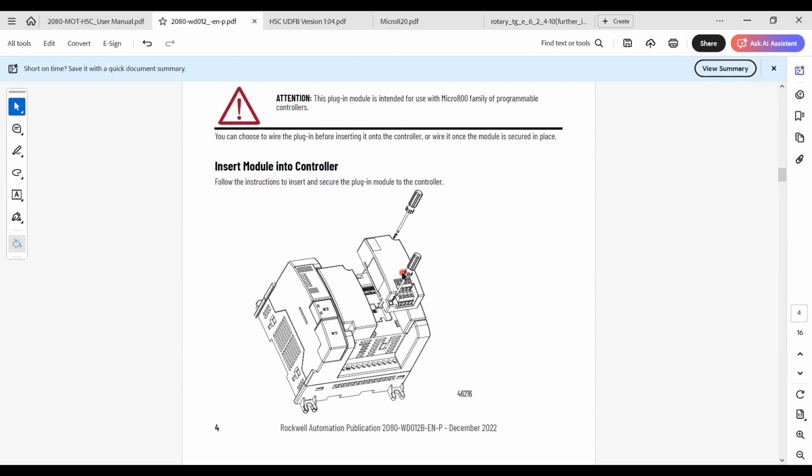If you use a normal counter in that application with a digital input, normally we cannot capture all the counts because it depends on the PLC scan time. When the speed is high, there is a high chance that the PLC scan will not count all the pulses. That is why we need to use external modules, or some PLCs have high-speed counters internally.